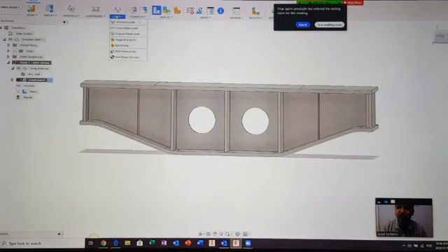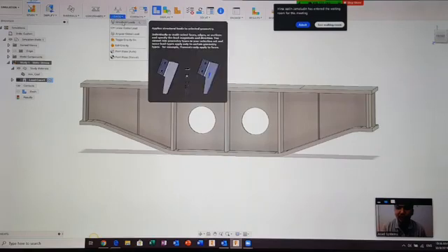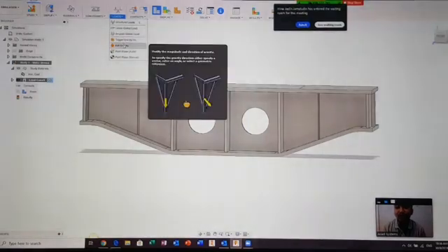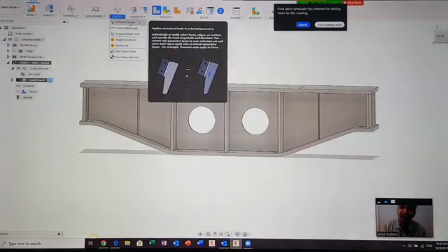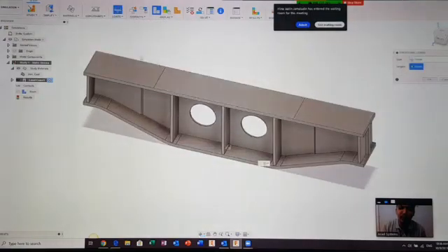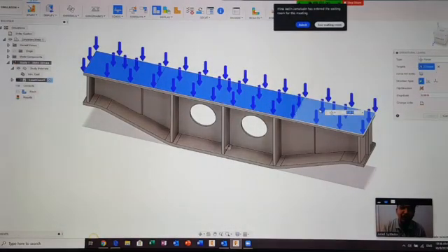Inside load, it has several functions. You have structural load, linear global load, angular, toggle gravity, which means you want to add gravity inside, and point. Let's say here I'm going to use structural load, and then I'm just selecting the face up here. Three faces here for the load to have. And for the magnitude, I'm going to make it maybe 10,000 Newton, which means alright.